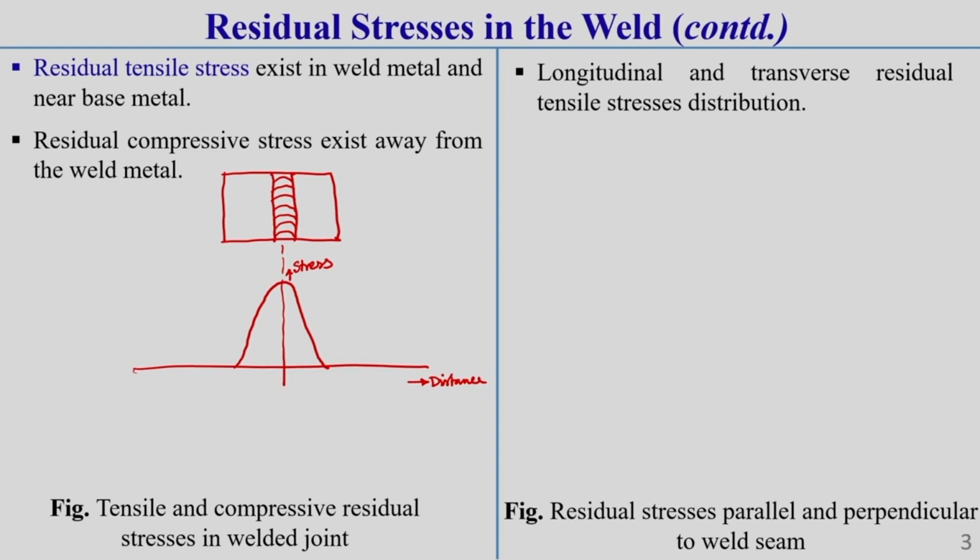Now, as residual stress is a balancing force, this weld zone is subjected to tensile force, but this force is supported by the surrounding material, so the surrounding material will be subjected to compressive resisting force, or compressive residual stress. That is why the residual stress will be distributed like this. Let this plate have this much length, a particular portion I am showing.